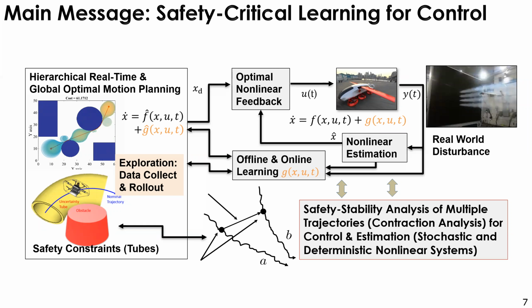I'm saying here that we can also accommodate some learning-based method to improve the accuracy, optimality and safety of your motion planner. Because obviously, if you use optimal control-based motion planning, then your trajectory is only as good as your dynamics. So there could be an actual violation of your safety if you don't have accurate dynamics when using the optimal control.